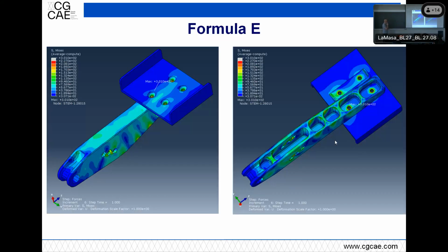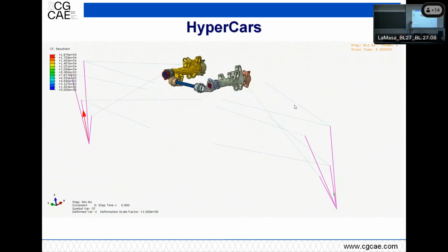I remember when I was in Toyota, and we had the telemetry data from the pressure in the brake system, Jarno Trulli was pushing almost constantly 140 kilograms. And in hard brakes, he could reach almost 200 kilograms. And the guy is weighing, I don't know, 65, 70 kilos. So it's really pushing against also the seat. And yeah, there are no rules in here. So everybody is doing what they think is sensible, but it's clearly something dangerous. I mean, you cannot really fail a brake pedal.